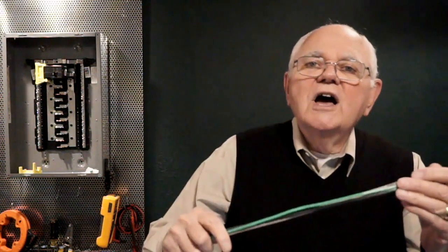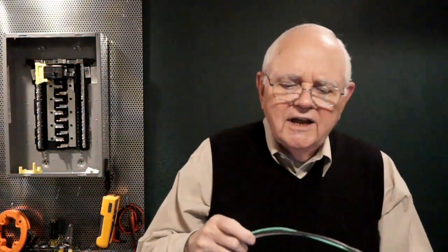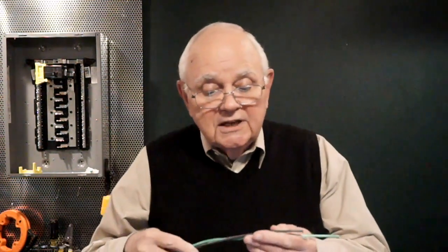Also, it matters whether I'm going to use this insulation in a dry, damp, or wet location. Dry, damp, or wet. So if I use this insulation in a wet location, they don't want me to carry as much current flow as it will carry in a dry or a damp location. So on Table 310.16, and why is that? Well, the insulation properties are going to change depending on the amount of moisture available around the insulation. For instance, actually the nylon jacket does absorb a fair amount of moisture.